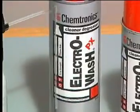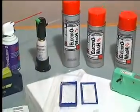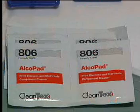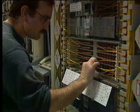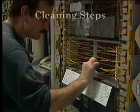A variety of products have been developed over the years to address the issue of connector cleaning. These include canned air products for blowing away dust particles, cleaning pads soaked with alcohol or other solvents, cleaning swabs for sleeves and bulkheads, as well as a number of dry and adhesive tape products to remove contaminants from connector ferrules. Regardless of the type of connector or the system where it is used, the basic steps for connector cleaning